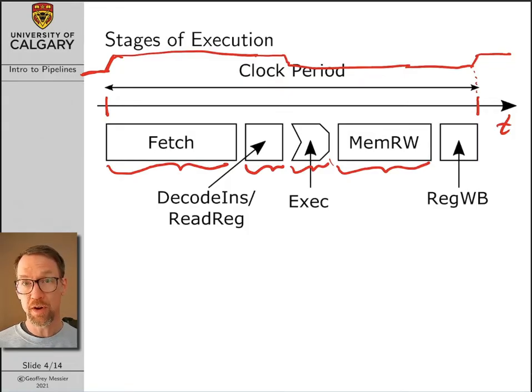The AVR microarchitecture does use pipelining. It uses a simple two-stage pipeline, and you'll see what I mean by stages as we get into the lecture. But even though we're using AVR machine language, I'm going to start representing this microarchitecture like it was a little bit more sophisticated than our AVR design.